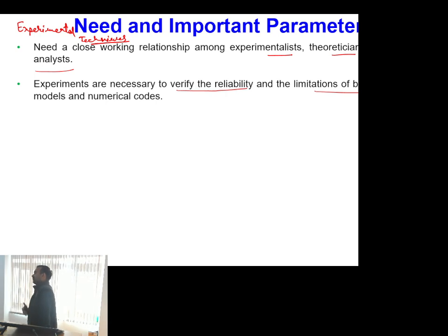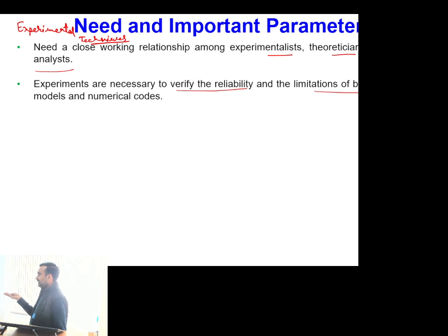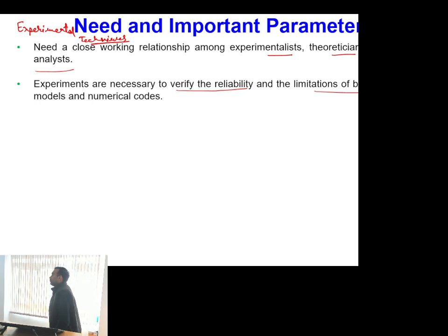So in terms of pure theoretical analysis, for example, if we have to only simulate flow through a pipe, we make so many assumptions. For example, Newtonian fluid assumption, then fully developed laminar flow assumption, then steady flow assumption, then flow is entering parallel to the pipe. So many assumptions we have made. And in terms of numerical simulations also, though we can actually analyze the developing flow through numerical simulations, in numerical simulations also we have some associated errors in the form of discretization error, etc. Okay, so numerical solution is also not foolproof, like it's not 100% accurate.